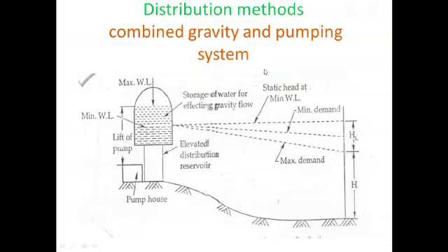What are the advantages then? Let me describe those. The balancing reserve of the distribution reservoir can be supplied to the places of fire, and however the necessary pressure required for firefighting can be achieved by closing down the supply of some localities or by using motor pumps. In all modern firefighting squads, motor pumps are therefore provided.